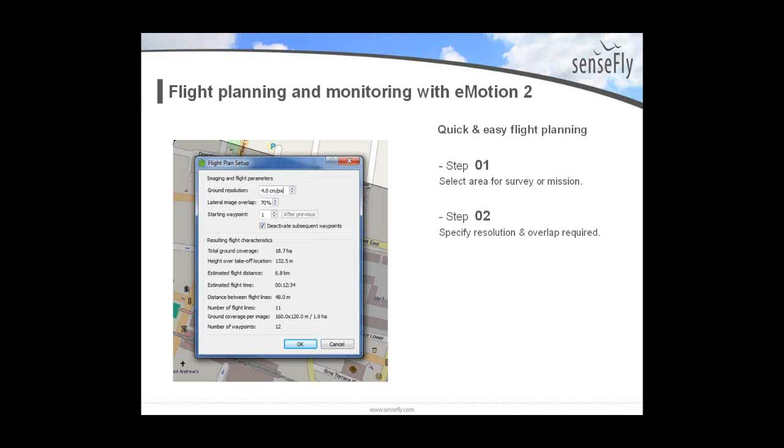The eBee will remain in contact up to almost 2 miles, about 1.5 miles, 1.75 miles with the radio system you have. So I wouldn't think you'd want it to go outside of that area. But you can pick that radius in the software. You also pick a ceiling, and with the FAA regulations, you've got to keep the eBee under 400 feet. 400 feet or under. So we typically choose about 130 meters as our maximum height.